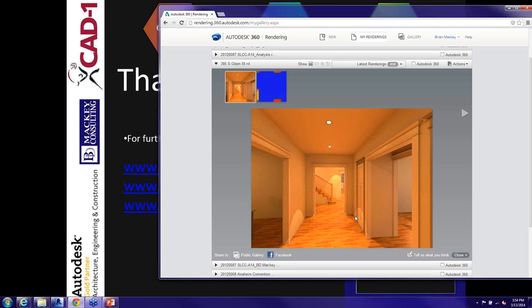And just truly quickly doing this draft rendering, you'll see this draft rendering of the entire thing took 2 minutes. So my little information there tells me when it was done, how long it took, what's the image size, et cetera. Well, and doing it this way doesn't eat up your cloud points. And that's the big thing until you're ready to do the final render. So just a quick rendering like this, as Stan said, 0 cloud points. Draft or standard renderings, as they call them, no cloud points. So just coming in and hitting this, that's all it's going to take.